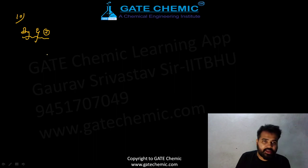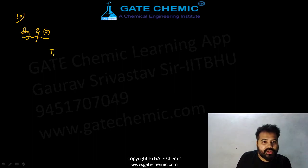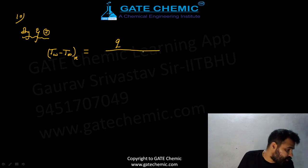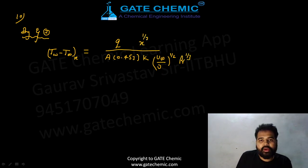Equation 2 was, I am writing again, Tw minus T infinite at x, आप भी मिला लेना, equals Q upon A into 0.453 K U infinite by nu to the power 1 by 2 Prandtl number to the power 1 by 3 x to the power 1 by 2.